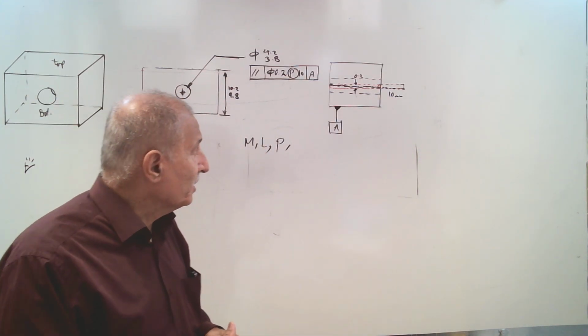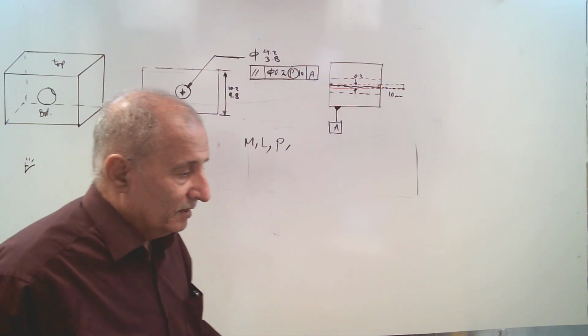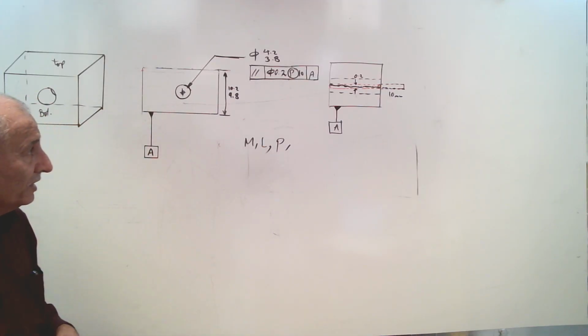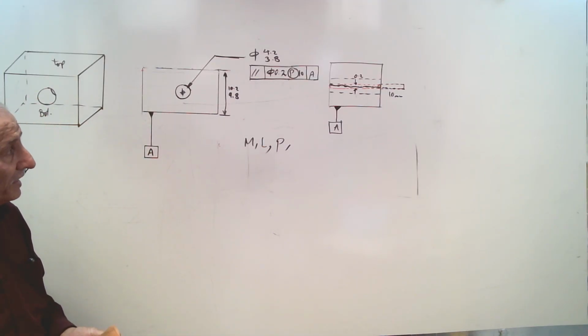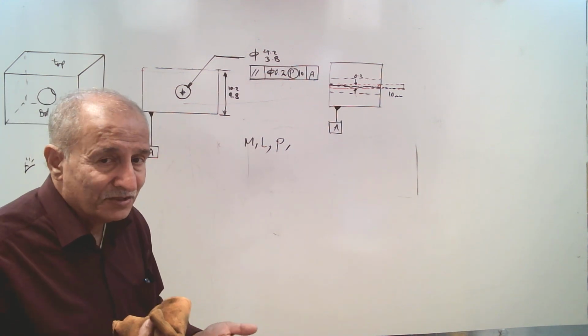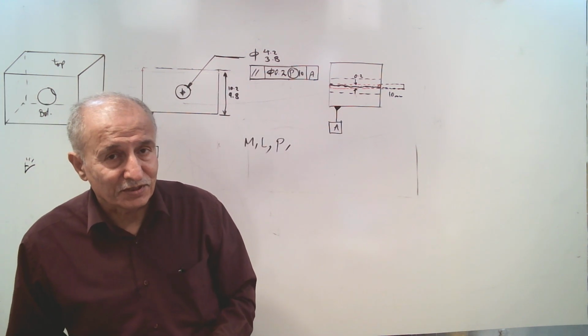And also for another feature of size, before I go to the center plane and apply orientation tolerance to the center plane, I must explain M and L. You know M and L send 3 messages to the manufacturer: rule number 1 does not apply.